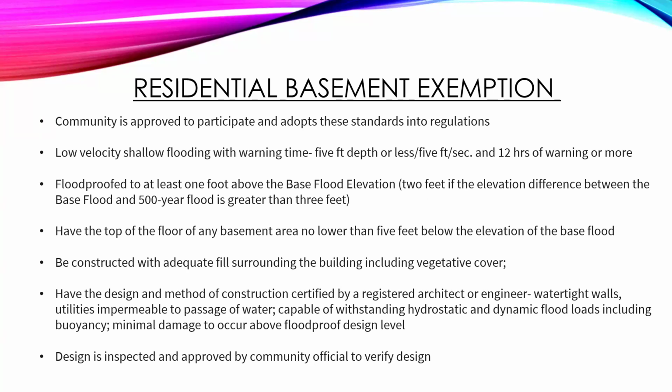And so I've kind of listed those requirements out. So again, you're approved to participate in that program. It has to be low velocity, lots of warning time. The basement is really just like 5 feet below the exterior grade. So it's technically a basement, but not like a true basement. Floodproof to at least 1 foot above the base flood elevation. Have the top of the floor of any basement area no lower than 5 feet, right?